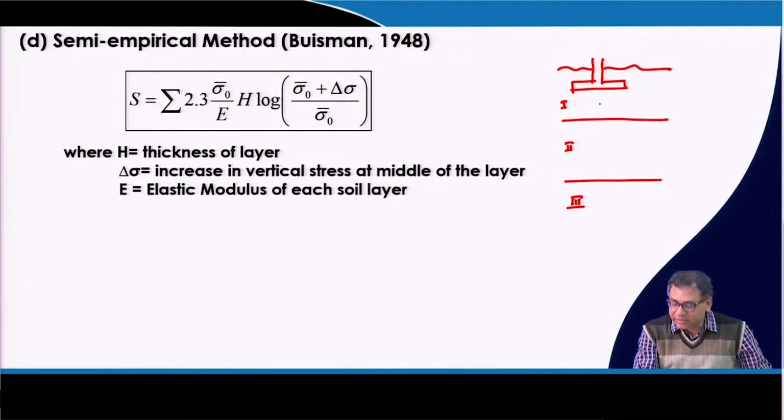So, we have to take a point in the middle of each layer from the base of the foundation up to the influence zone.